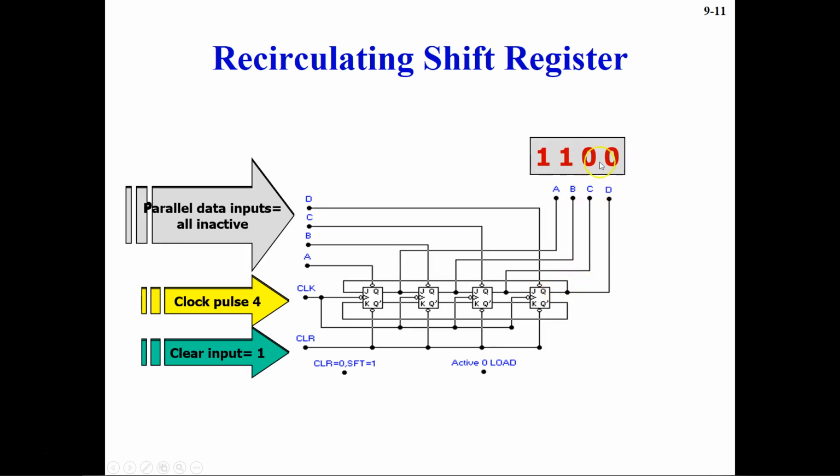This will change to 0 because now the next input which this D flip-flop got was 0. So if this is 0, J is 0, then K is going to be 1 because Q bar is opposite of Q. So for this case, at that point your J is basically 0 and K is 1, and when you have J 0 and K 1, then your Q is going to be 0.